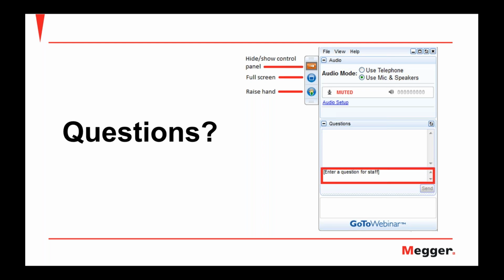However, if you're measuring the float current in the battery and you know that battery is in float mode, specific gravity has limited applications. Where you really want to make sure that you're measuring specific gravity is when you have flooded lead antimony batteries. Those types of batteries can suffer from antimony poisoning, and the specific gravity will help you see that. But other than that, if you have a lead calcium battery, as long as you're monitoring float current, you don't necessarily have to do specific gravity readings.